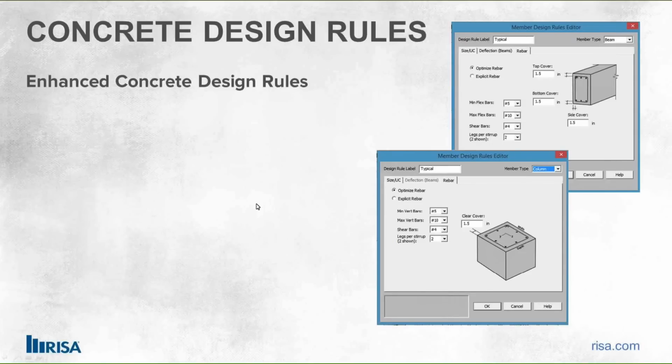If you're not familiar with using concrete in RISA-3D, for example, we use design rules to help define how the program is going to design the reinforcement. In steel, we talk a lot about sizing things. We size up the members, and we do that with wood as well. But in concrete, a lot of times the size is defined by the architect or the layout. What we're doing for design is the reinforcement. So you can size the shape up and down, but more often you're interested in sizing that reinforcement.